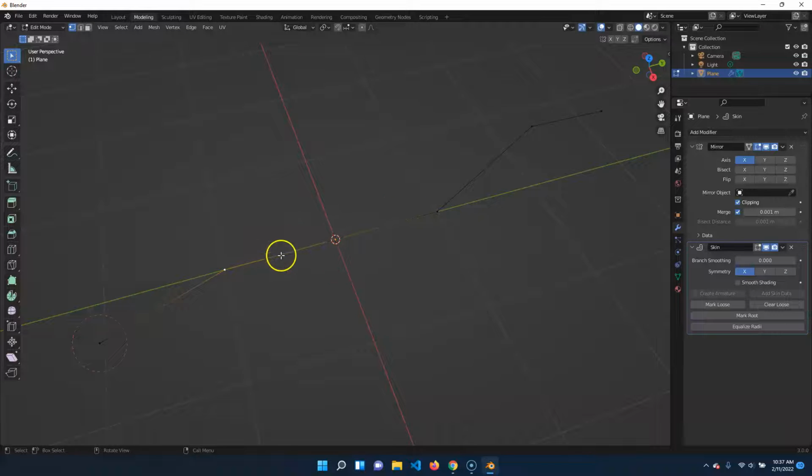So, yeah. What we're going to do is put some on the inside. Well, maybe we do want them just here and here. Yeah, we'll just do it like that. So I'm going to grab this and I want to extrude. But if I try to extrude this, it won't allow me because I have clipping on. So you want to make sure you turn clipping off first.